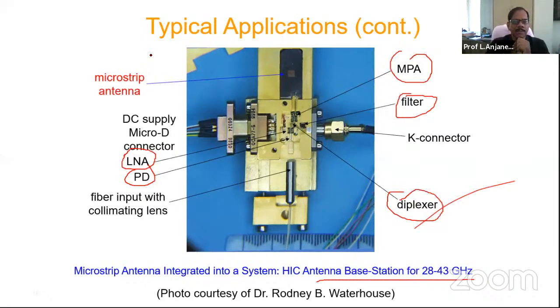So typically you see a kind of board. For high frequencies, we use FR4 based or RT Duroid based designs with the substrate thickness varying. So the boards look like your printed circuit boards, but the thickness will vary. For my typical microwave designs, they may have a thickness of about 1 mm, 1.6 mm, sometimes even 2 mm as the thickness of the antenna structures. But at high frequencies, as you go, the thickness will reduce to less than a millimeter.